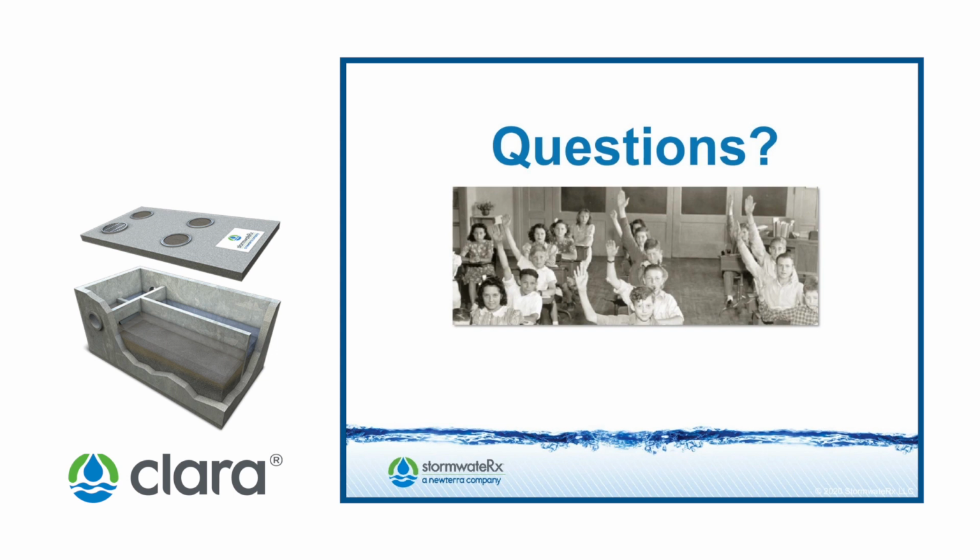So we are sticking with removal of solids and any pollutants that are associated, non-aqueous phase pollutants. So that might be metals that are in the solid phase, even nutrients that are in the solid phase. So in general, yes, we do expect that there would be some level of zinc reduction if there's non-dissolved zinc, as there typically is some portion. But in general, yes, just solids removal.